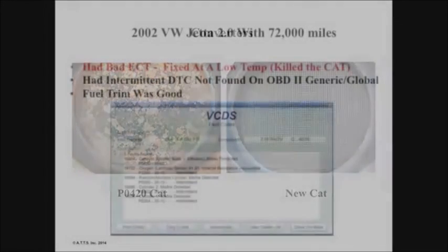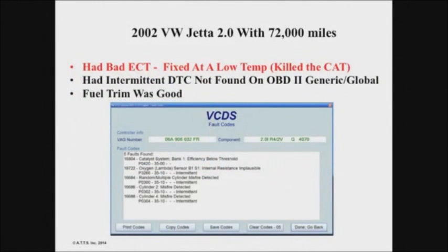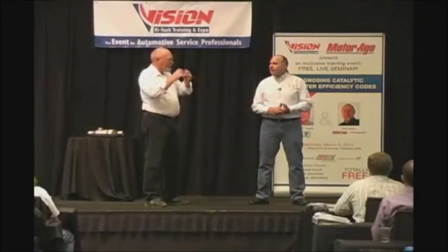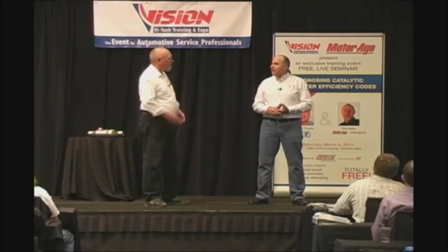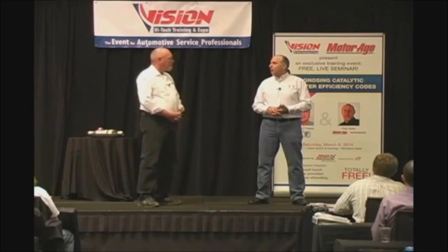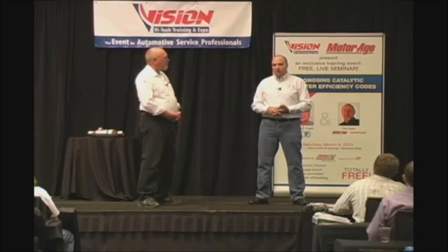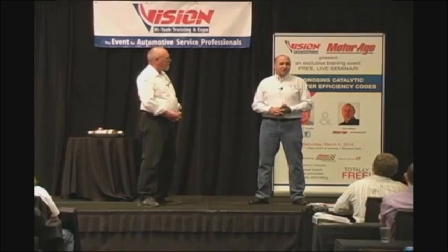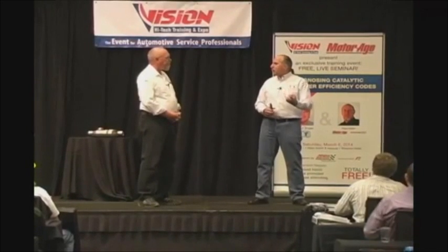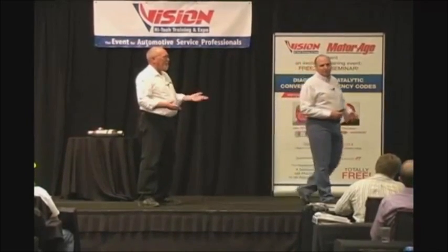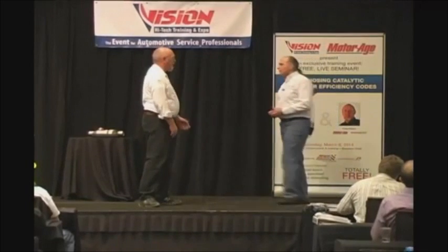I got to ask, G, it's interesting. We always use the term clog, cat. What's it clogged with? Or is that clogged, or is that actually those little individual cells trying to melt down on each other? Some of it is melting down, and some of it, depending if it's burning oil or whatever, sure, some ash and so on, but they do melt. They sinter big time. I've had some I took out, they look like just a ball that someone just crushed together.